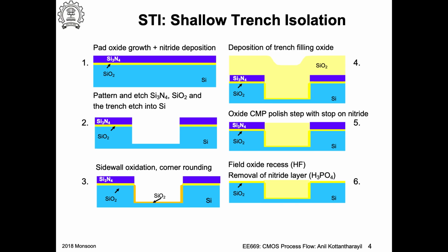And the lower part, the starting wafer, is usually CZ, so that is a Czochralski silicon grown wafers, right? And this process, when you actually want to build this integrated circuits, what you do is you buy these wafers where epitaxial silicon deposition is already done. Okay, so we would refer to this wafer as the silicon wafer, but keep in mind that usually they have on the top part the silicon is epitaxially grown, so that you get a high quality silicon.